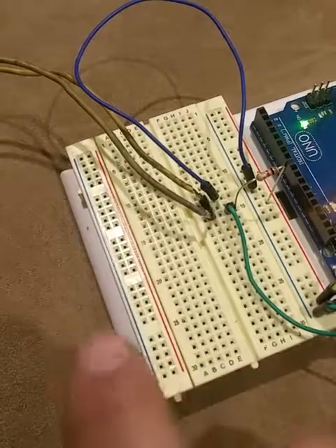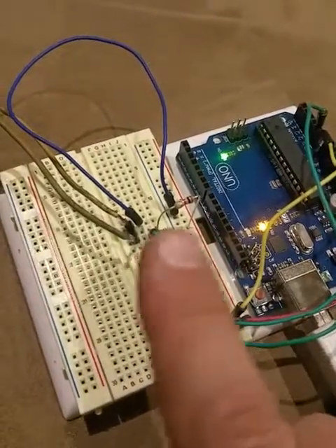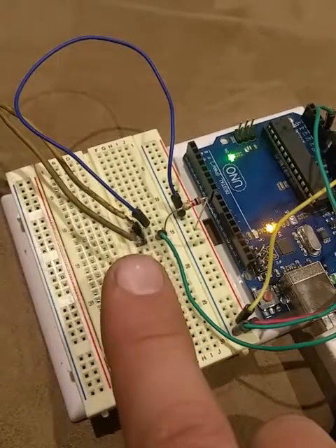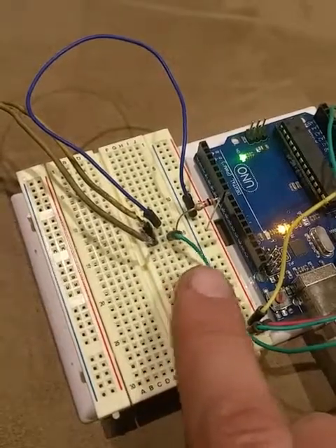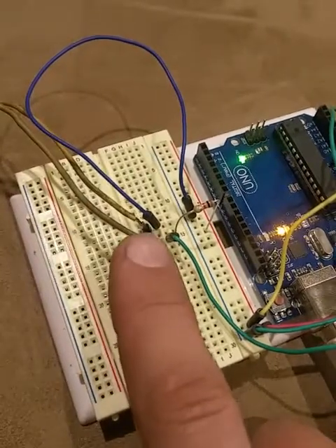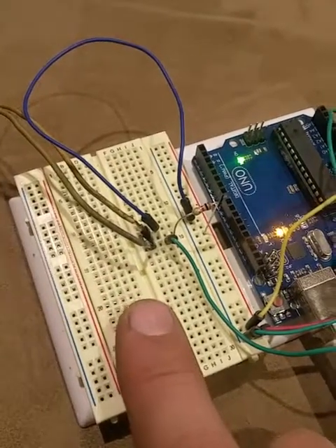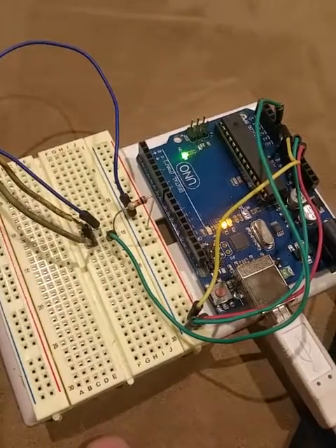Basically this is a voltage divider. So I've got one resistor fighting another resistor, and the voltage between the two will change with the temperature on the sensor. Because of Ohm's law, I know the value of this resistor is never going to change, but the value of the temperature sensor is always going to change depending on temperature. So using Ohm's law, I can figure out from the voltage I read here what the resistance of the sensor is. And with the resistance I measured off the sensor, I can then calculate the actual temperature. There are charts all over the internet for it, and I think it's publicly documented on a few GM websites.